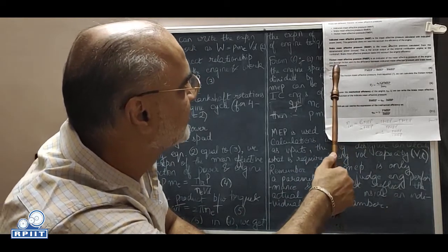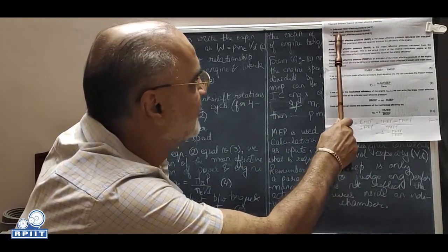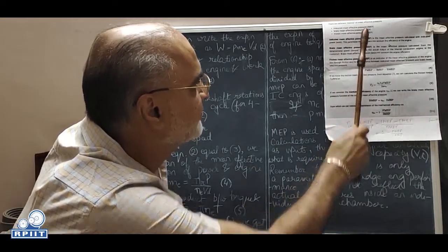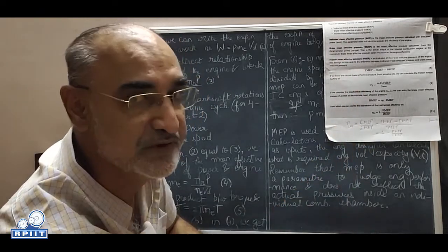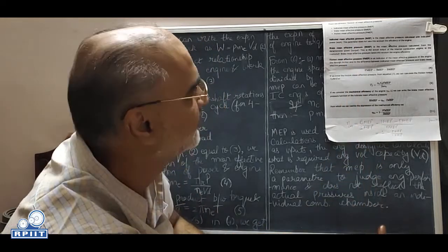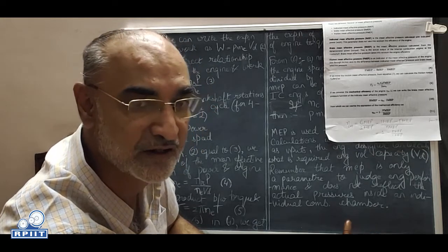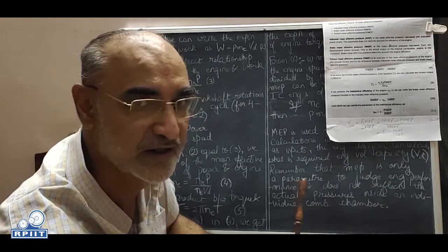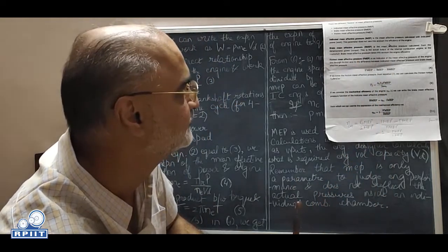Now there are different types of mean effective pressures: indicated mean effective pressure, IMEP; brake mean effective pressure, BMEP; and friction mean effective pressure, FMEP. What are they? Indicated mean effective pressure is the mean effective pressure calculated with indicated power, the power from an indicator diagram. We know that when you draw a PV diagram, the area inside the curve is the work. This parameter does not take into account the efficiency of the engine.